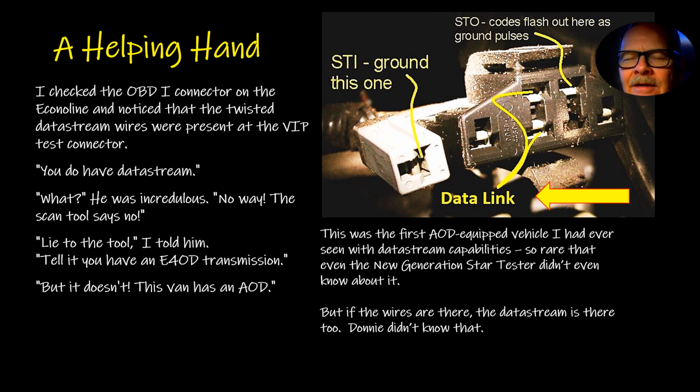And I had run into this a couple of times, it seems to me, but I found out that if you look at that connector, regardless of what transmission or whether you've got mass airflow, and it's got data stream wires, they won't be dead. If those wires are there, that thing will have data stream. And he was basically shocked that he had data stream the whole time he'd been fighting with that thing.